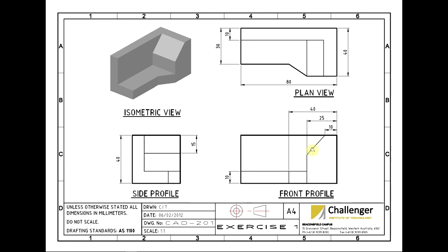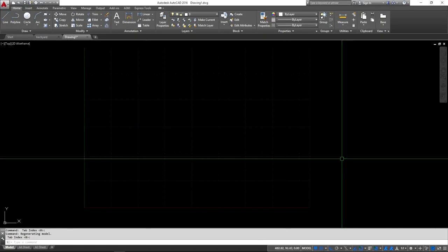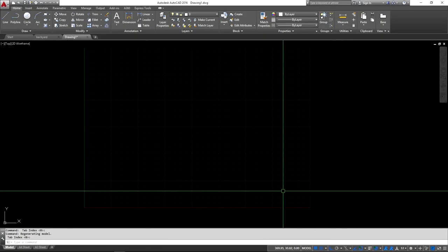So that's pretty much a 45-degree angle, so 15 in, 15 down. From there straight down, up 10 across, and from there we're 40 across. So just keep in mind all those measurements. You can flick back and forward between your drawing and your AutoCAD page to do this, but I'm not going to do that because I know all these measurements off by heart.